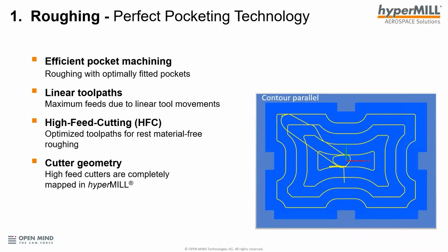As you can see, what has been a trend in the past is to make a roughing cycle, a roughing toolpath. The way this is done, and we're looking at the toolpath in this picture on the bottom right, is that you take a section through the part, and then you offset that section by the tool radius or the step over.